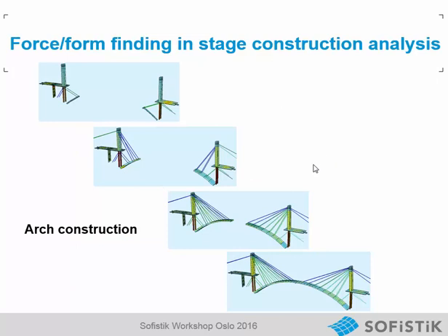We have also other stage analyses possible here. We can have additional help pylons on an arc bridge again, and again if you have an analysis where the two cantilevers do not come together in the first analysis, this is never a problem, because the precamber is very cheap, and the precamber does not change the forces or bending moments in your system.